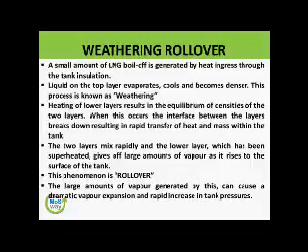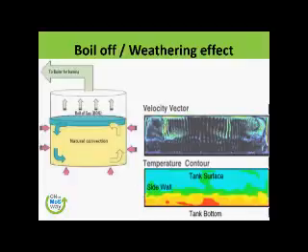So I have explained you this whole lot. So you are happy with it? Any questions with regard to rollover? So it is your job as an engineer to maintain it. So this is just a boil-off and weathering effect. This is becoming heavier. Suddenly it goes down. The other liquid comes up, and this is a very nice density. And of course, this is a pure tank. This is the thermal image.